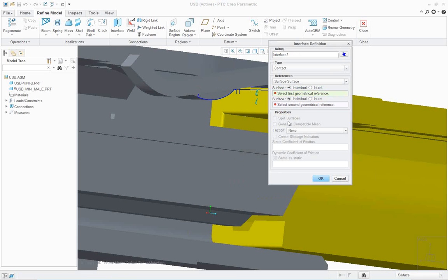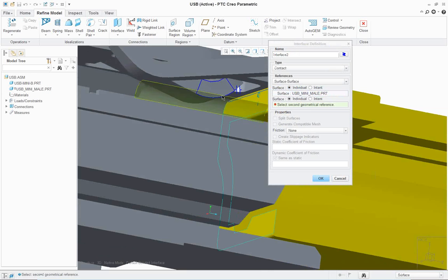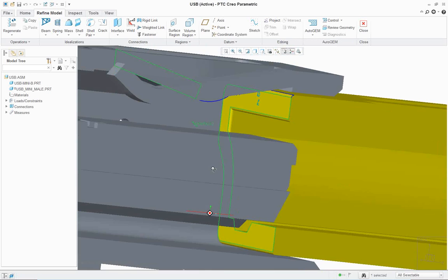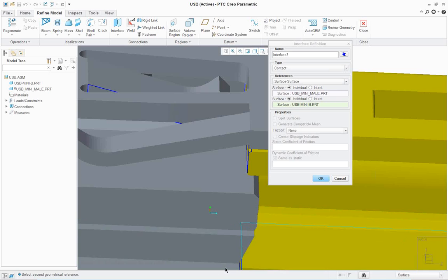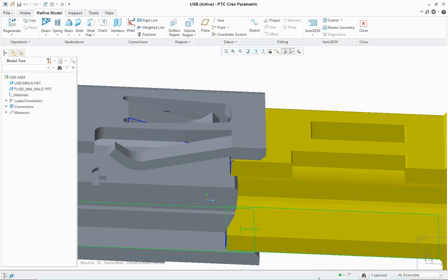Now all I have to do is press the map key button, and then begin to pick multiple surfaces. I can do that here, and then do that. And so it basically minimizes your mouse travel time, and you can just directly focus on picking those surfaces to set up. Technically it's not as simple as picking those surfaces in groups and just specifying the contact between the groups, but at least it still saves you a good amount of mouse travel time by just having to press the buttons and it activating the command for you.